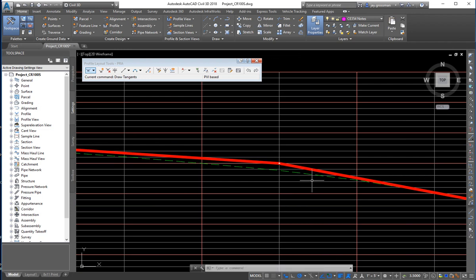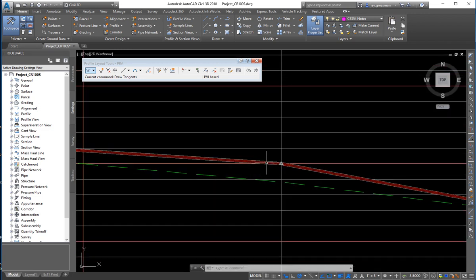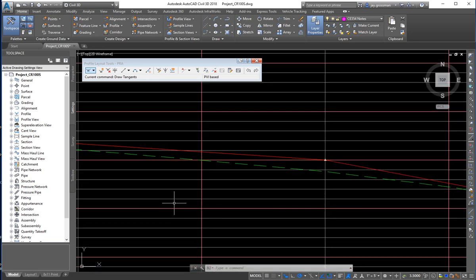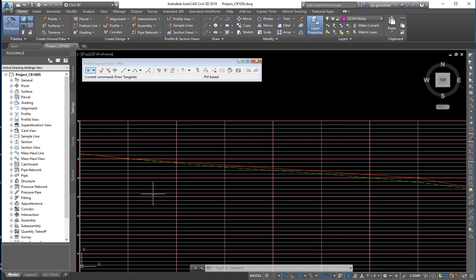And if this big line, this red line is too fat for you, and it's blocking things down here, there's a show hide line weight. You can turn that down. And now it hides the line weight. Now on your final prints, you want that to be a big bold line. So we show it that way. And for design, it can probably get in the way.